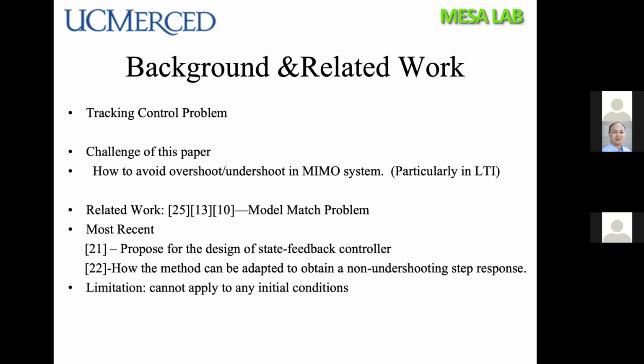Well, this case is easy for SISO systems, but the challenge for the control method the authors developed and implemented in this paper is how to avoid overshoot and undershoot for the MIMO system. The authors show in particular that in the case of LTI MIMO systems, it is possible to achieve arbitrarily fast settling time and also a monotonic step response in all output components for any initial condition, which implies the avoidance of overshoot and undershoot even in the presence of non-minimum phase invariant zeros.